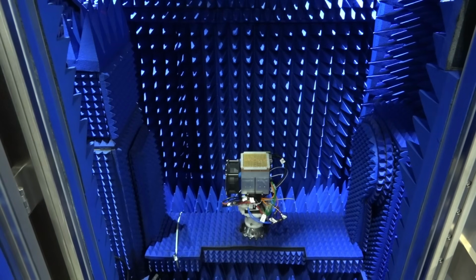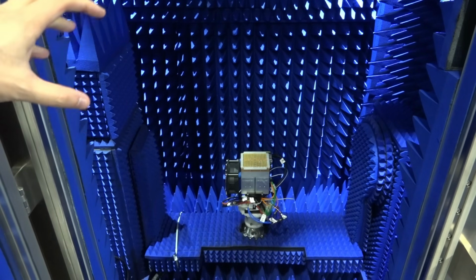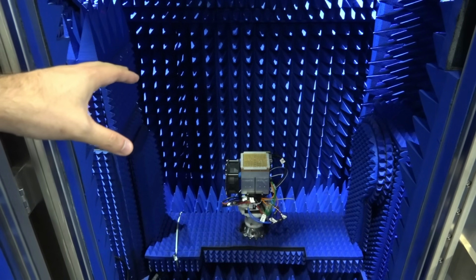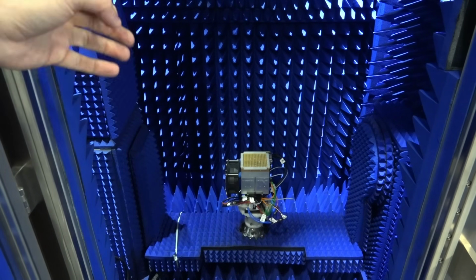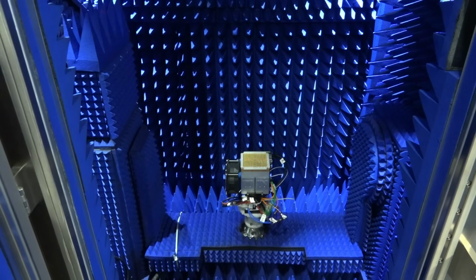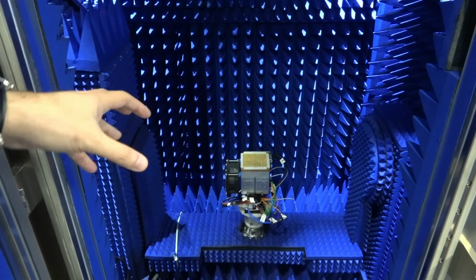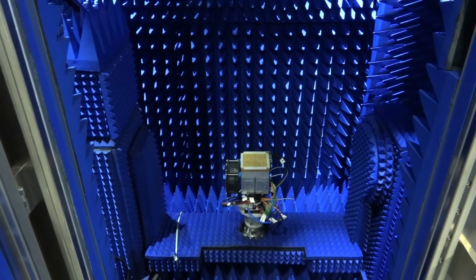So here at Keysight, we also have another turnkey solution for measuring radiation patterns and other characterizations of the device. Now the challenge with this kind of measurement is always the same. The problem is that the measurement plane has to be moved to the edge of your device in order for that measurement to be helpful. And normally over-the-air measurements always have so much uncertainty, because you don't know where exactly the reflections happen, where the measurement plane is, where you have done your calibration.